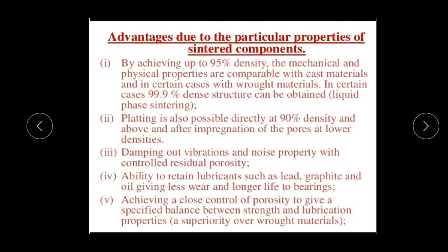The fourth one is the ability to retain lubricants such as lead, graphite and oil, giving less wear and longer life to bearing components. And the fifth one is achieving a close control of porosity to give a specified balance between strength and lubrication properties.